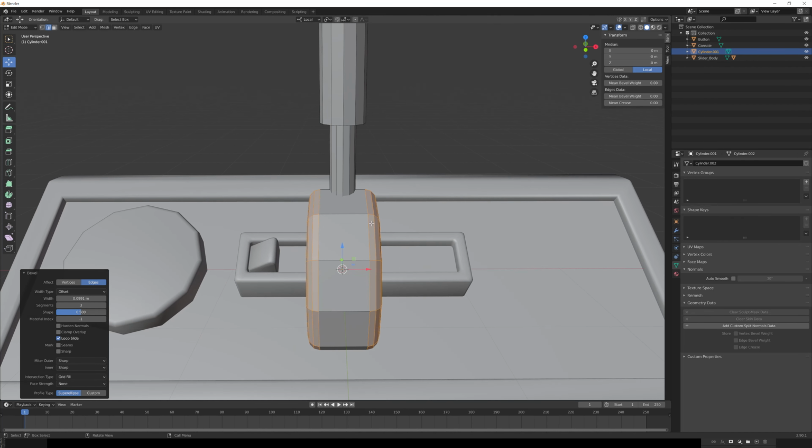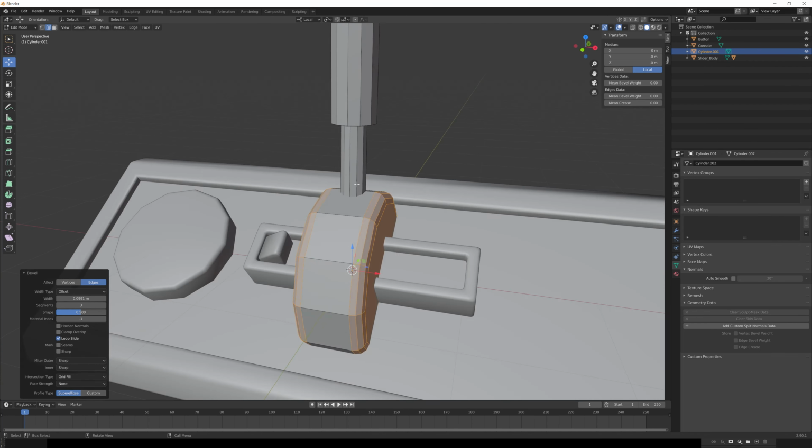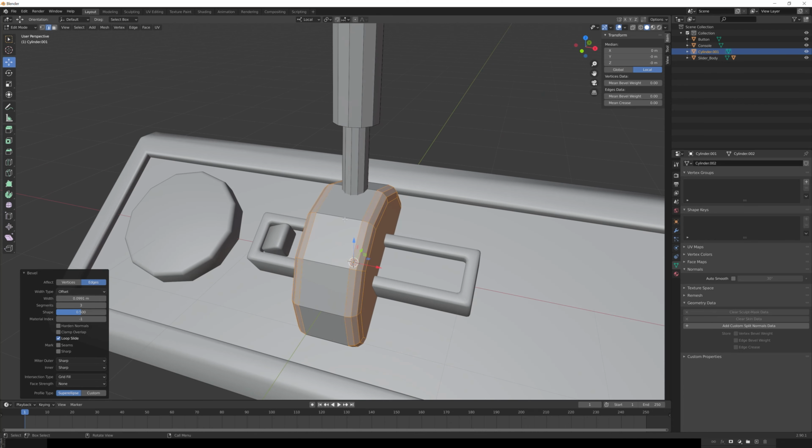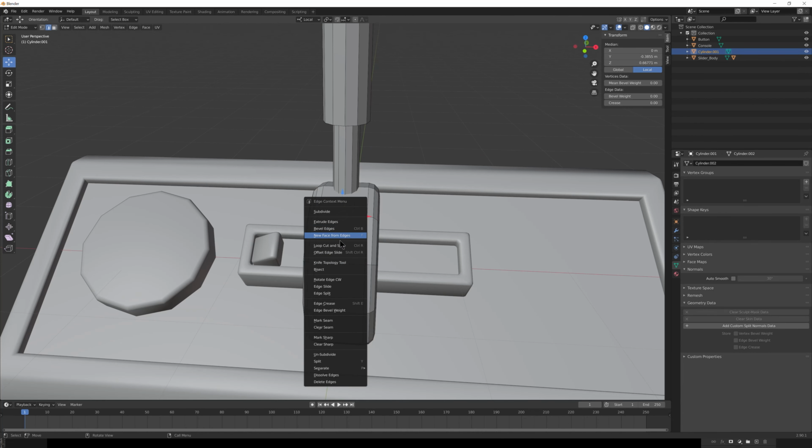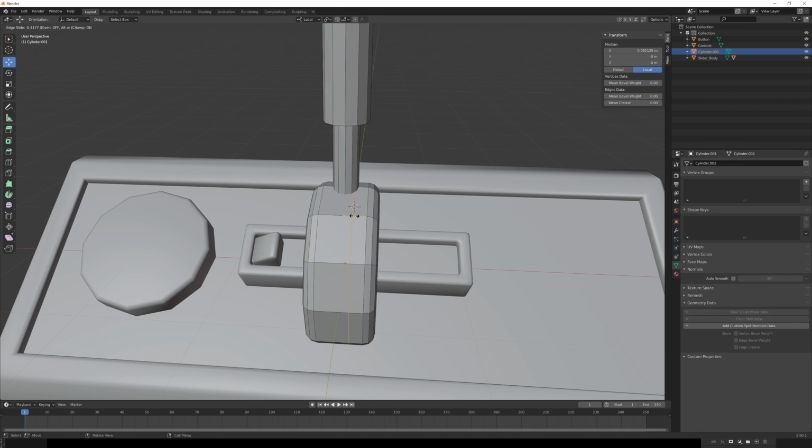And if we also want to, we can add a central channel, which this lever arm seemed to have been a part of. And either the lever arm can rotate or the whole thing can rotate. It's really up to whatever you want to do. So let's go to edge mode in this case, actually, and right click and do a loop cut down that central point. It doesn't matter where, right there. If we right click, it'll go right to that center point, by the way. You don't have to move it. And we have the number of cuts. I'm going to make that 2. So I have 1 on either side. Go ahead and click off.